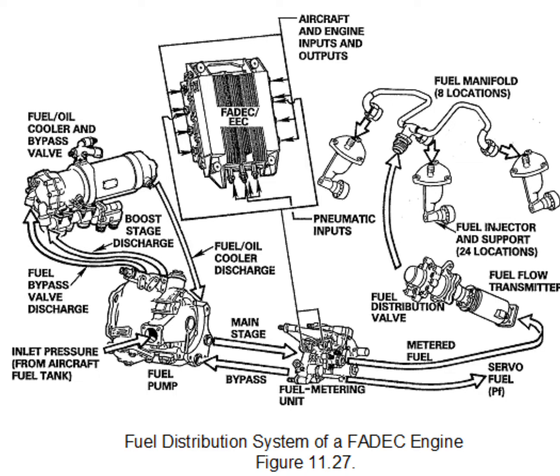What is meant by trimming a turbine engine? Adjusting the fuel control specific gravity for proper idle and full throttle RPM.